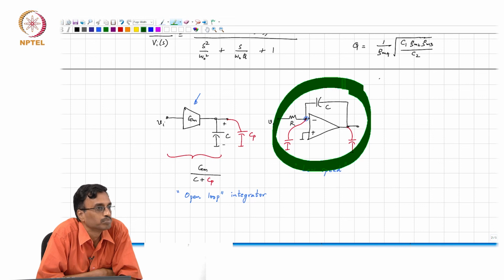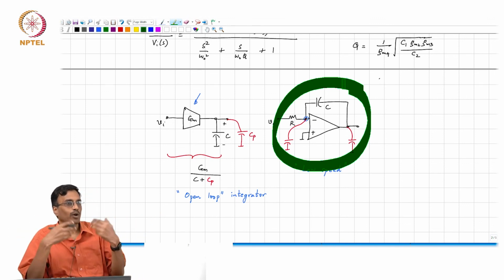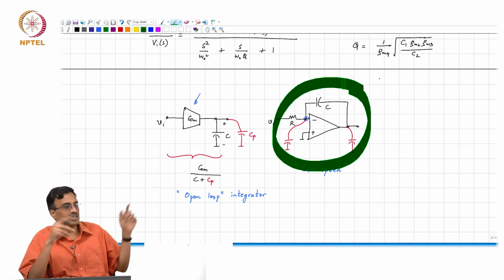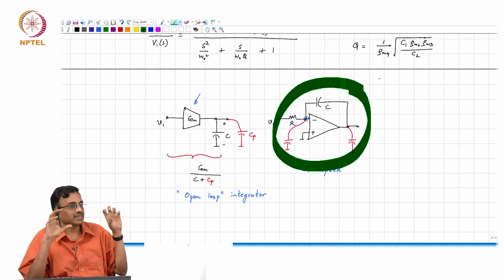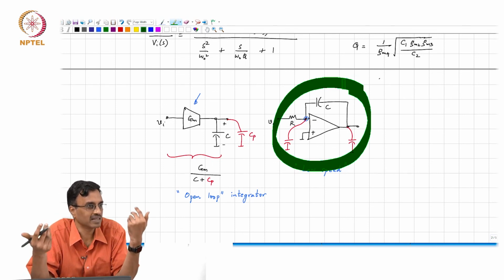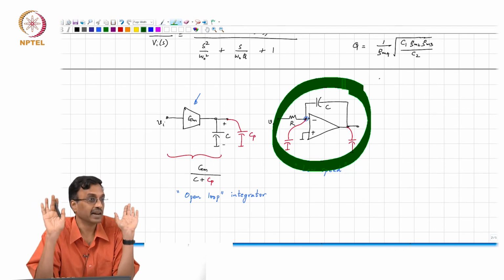Yes, Jishnu. Yeah, but an op amp needs several transconductors to make it work. Correct. A two-stage op amp, for example, has at least 2 stages of gain and all the associated parasitics. Whereas, at least in principle, the GM is simply a single transistor. The output parasitic capacitors of the transistor do not bother you because they could be part of the integrating capacitance, because those parasitics appear in parallel with C. It is not robust, but it integrates.